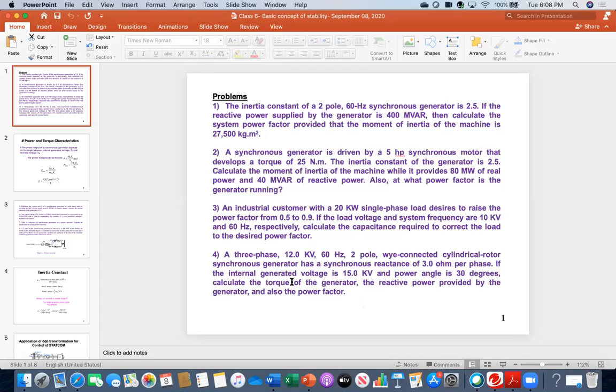So the power is 30 megawatt. Okay, we have the P value. 30 megawatt, right, that is right. So everybody, as you see, Manoj said the P value is 30 megawatt, which is right. So the first question is, Manoj, find out what is the torque of the generator. Again, the torque equals power over omega. Power over omega.